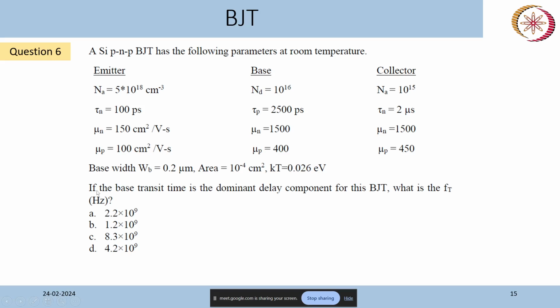Okay, if the base transit time is the dominant delay component for this BJT, what is the FT? Okay, what is the frequency of operation for the BJT?